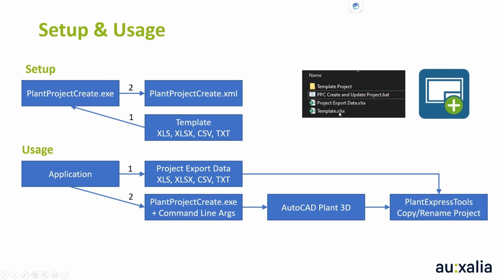Then you need a project template. And that's enough for us to get started. So what happens is, if you start PlantProjectCreate, which is an external tool, it's not running within Plant 3D, it runs outside, it will use the template file here to know which properties or which settings you have.